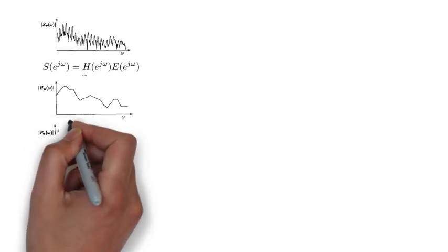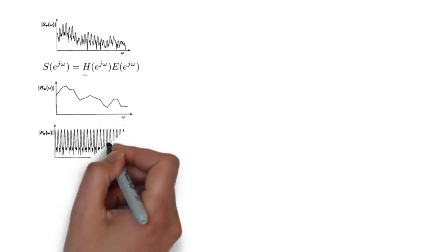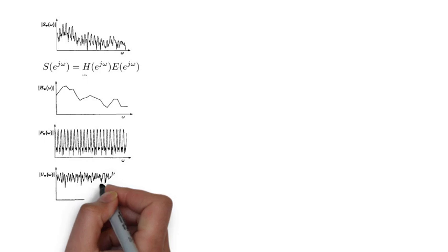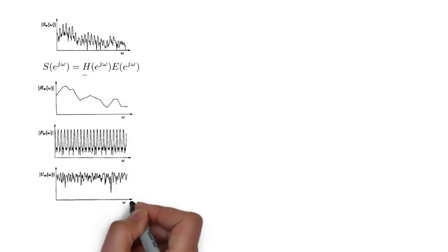The excitation can be either a voiced excitation, which is a set of window functions, each modulated up to a harmonic of the pitch frequency like this. Or it can be an unvoiced excitation, which is a random noise spectrum. And here's a particular instance of the magnitude of a complex Gaussian random noise spectrum. Looks something like this.